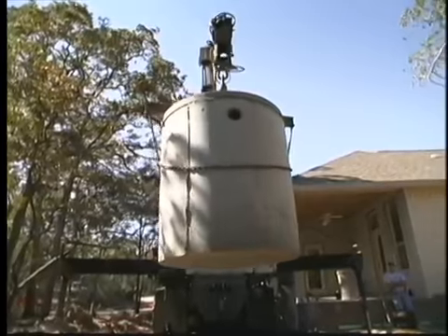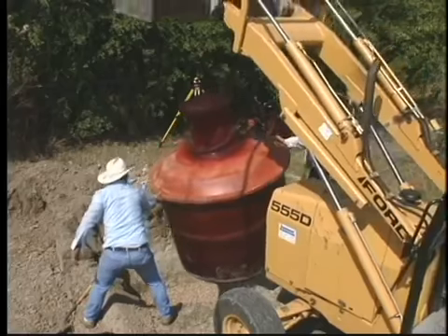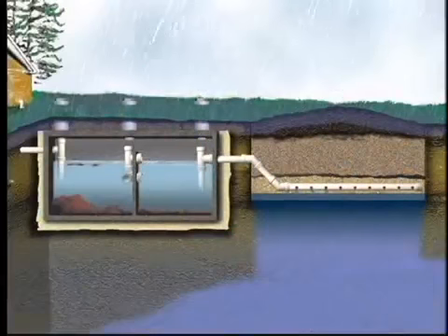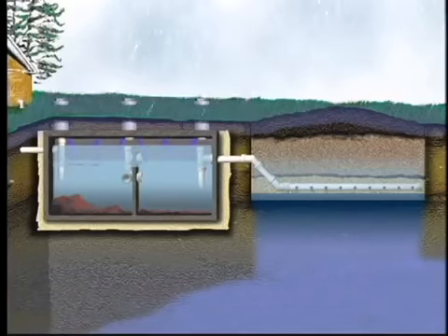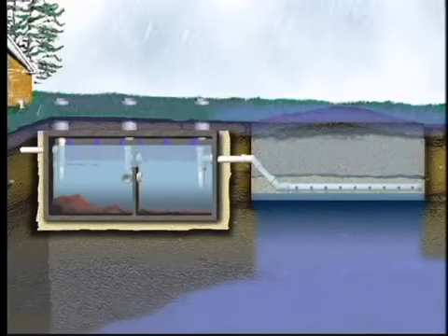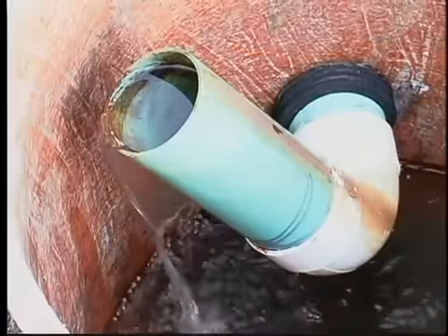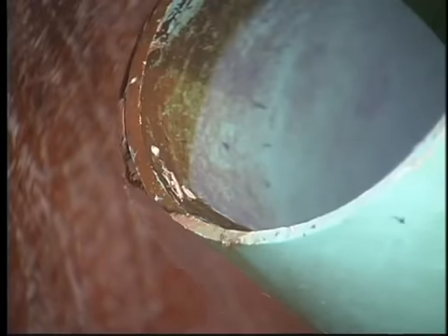Most septic tanks are made of concrete. However, fiberglass and plastic polyethylene tanks are becoming more prevalent. These are lightweight and ideal for hard-to-reach spots. All tanks must be watertight to keep water from entering the system, because excess water entering the system can saturate the soil absorption field. The result is water flowing above the ground surface. Using a septic tank to pre-treat sewage allows secondary treatment systems to work more effectively. The effluent emerging from a septic tank is mild, consistent, flows easily, and is better treated by both aerobic and anaerobic processes.